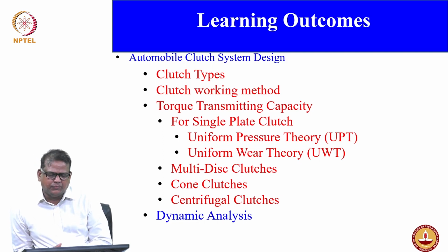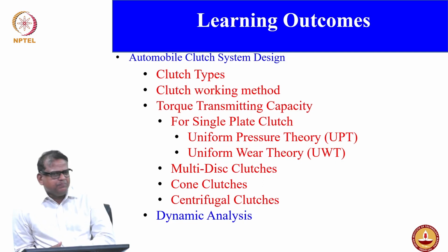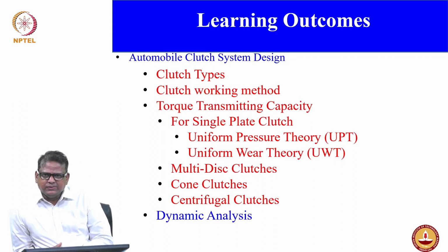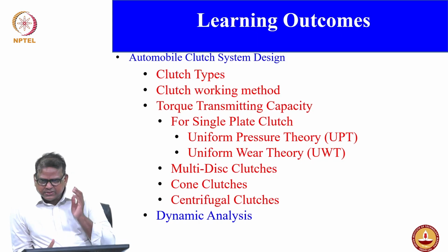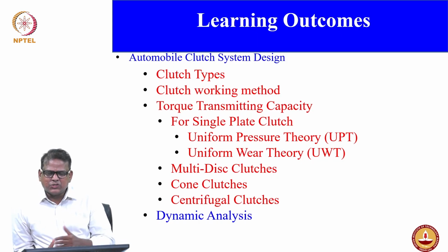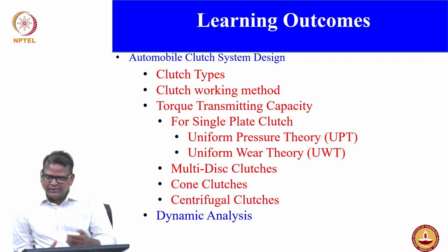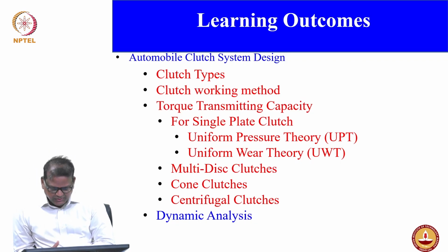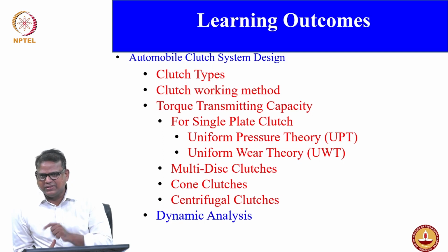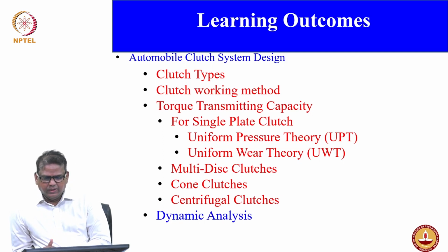It's not only about the vehicle dimension, the vehicle weight, and the speed, but also three different coefficients of friction: one is your friction lining, the other is the road surface, the road adhesion coefficient of friction, and the third is your rolling friction. All those things are involved.